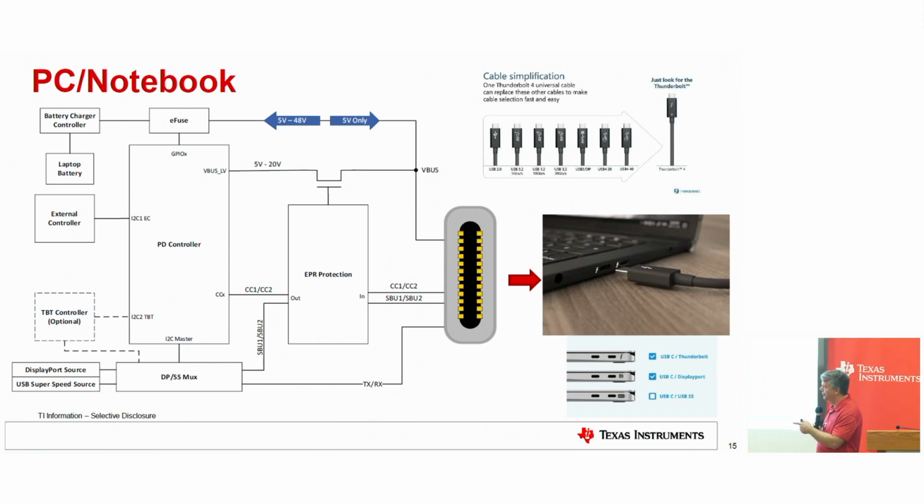Yeah, that's for if you have a Thunderbolt controller, say an Intel Goshen Ridge or something. That's handling the USB. It's basically like a big USB MUX as well. And that's for handling Thunderbolt muxing and all that through that controller. So the actual high-speed data lines run through that chip, and we're controlling the MUX on what to do.